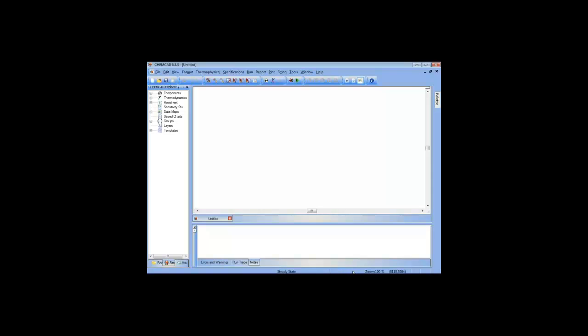What is the K value option that you're using, as well as the enthalpy option that you're using. When you do sensitivity studies and you have multiple steps that you're running through, that information will also be conveyed down here. So there's a lot of useful information down on this status bar as well.